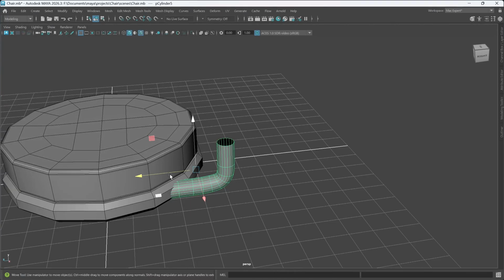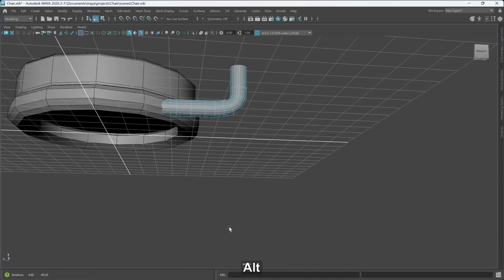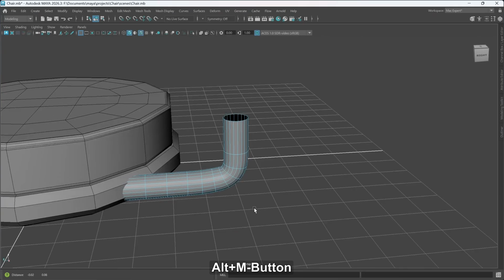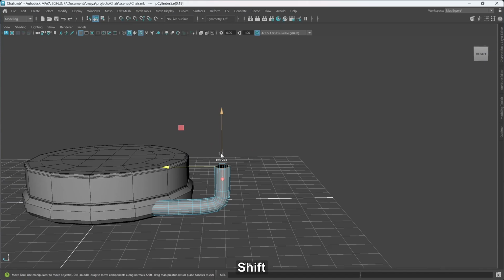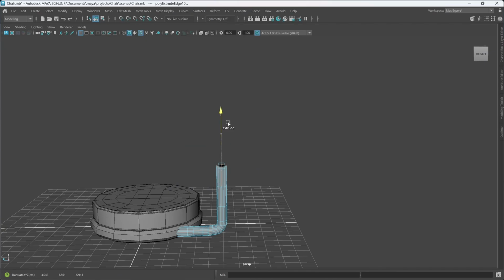And maybe let me take this out and just go into the edge mode. Double click to select this loop and just do one extrusion into the seat, into the ring. Okay, that is fine. Now we'll go into the edge mode, select this loop round, hit 1, just drag this up and also drag this up depending on how long you want it to be.